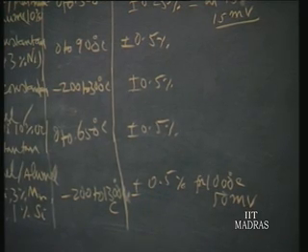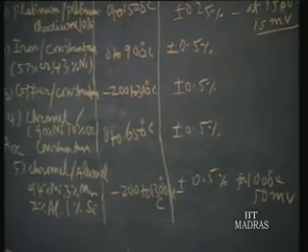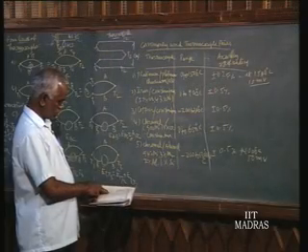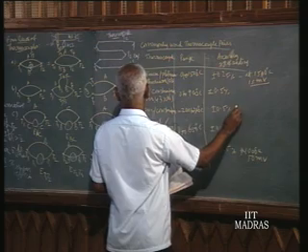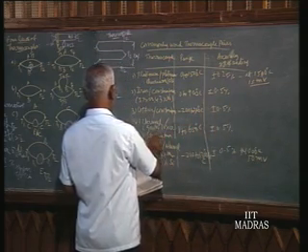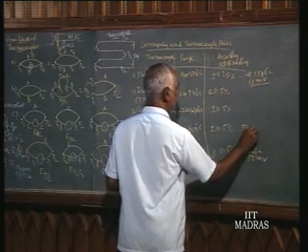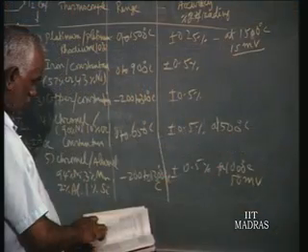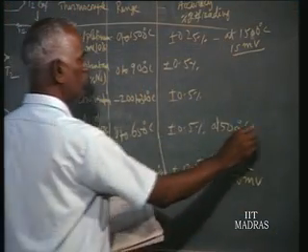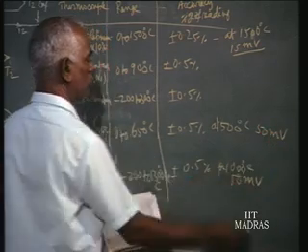The other one, chromel constantan, develops 50 millivolts at 500 degrees centigrade, so it is more sensitive.